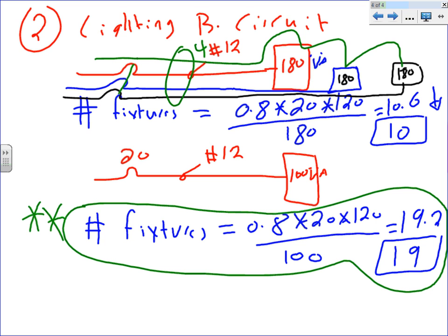And I move to the next room, I go 2, 4, 6, now phase A, phase B, phase C with a neutral, and you keep going. Then you go to the odd, even, and move always in 3-phase combo. Are you guys following me? As you circuit, don't just go 1, 2, and 3 in one area. Always in odds and in 3-phase combo.